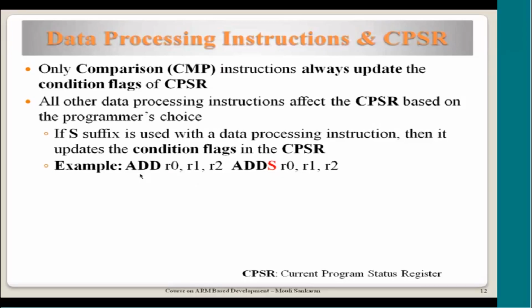When you write like this, the assembler interprets it as R1 and R2 are added and copied into R0. Now you know that when two numbers are added, it is going to impact the conditional flags of the CPSR register. What are the conditional flags? Carry flag, zero flag, negative flag, or overflow flag. Now when you write add R0, R1, R2, it doesn't change the values of CPSR. Though this addition could do it, it is disabled when the user has written just an add.